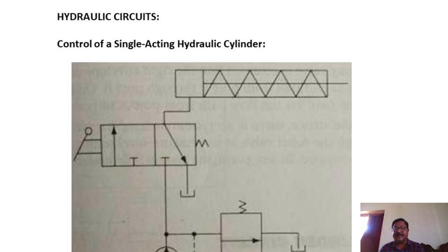Design of a hydraulic circuit is to select various elements and devices of required types, capabilities, capacities, efficiencies, so that the elements or devices carry out their intended function as desired and satisfactorily. Elements and devices include the oil of a certain grade and viscosity, pumps and motors, and connections with correct characteristics such as speed, displacement, efficiencies, and valves, hoses, joints, connectors, so that the system as a whole performs at possible peak efficiency. The hydraulic circuit not only contains pipes, but pipe connections, interconnections, all those things.